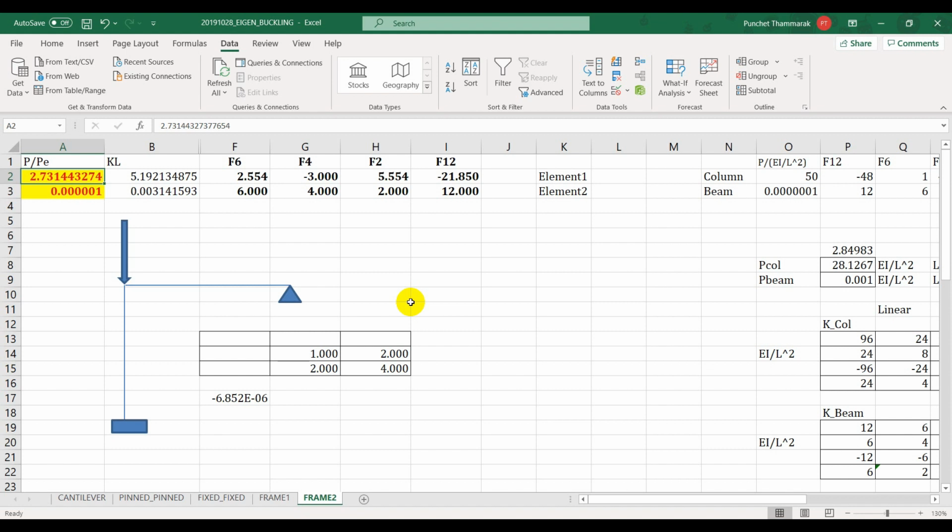And sometimes the function fluctuates, so it jumps at some value. The geometric stiffness matrix is better in that regard, so it is quite stable, it is not fluctuating much. But to use it and to make sure that you squeeze out the capacity of the geometric stiffness matrix as much as possible, you need to be very careful with the choice of your mesh.